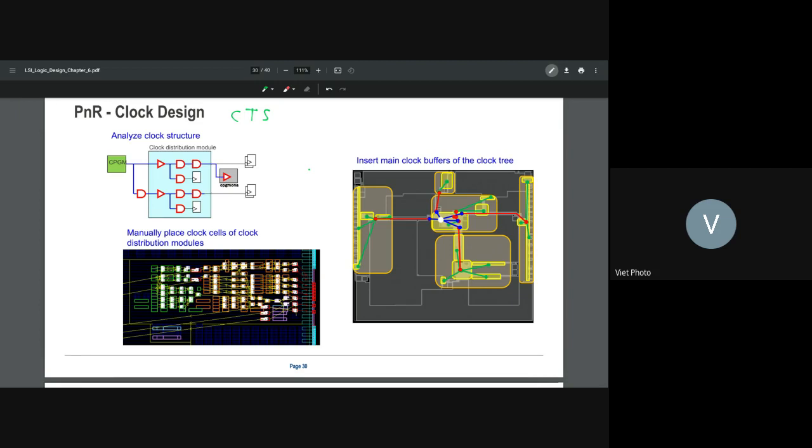So that means those parts will not be optimized equally, which means the short part of 4 stage won't need to be optimized because by itself it already meets the timing requirement. The other parts, like the 30 stages, is 1.2 nanosecond. We need to optimize it to meet the requirement of only 1 nanosecond. So how can we do it?